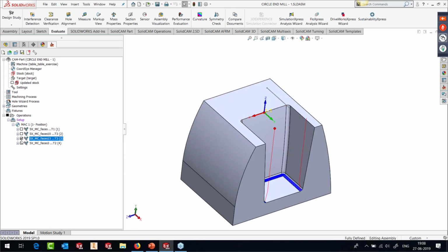So you can see that the circle end mills are actually going to revolutionize the way you cut 5 axis. They're going to reduce your time of cutting because they have got a very large radius. Bigger depth of cut, yet generate very small scallop, so your cutting time can really come down. So these were some of the very nice features that we get outside for solid.